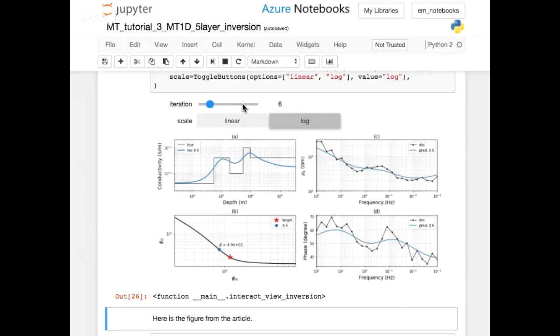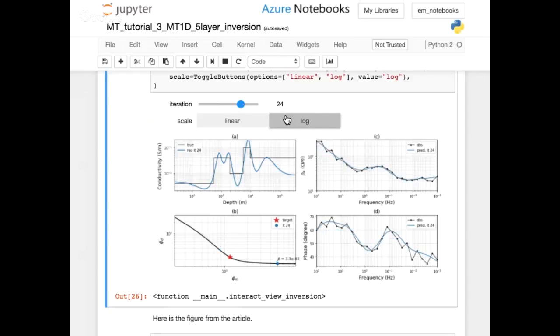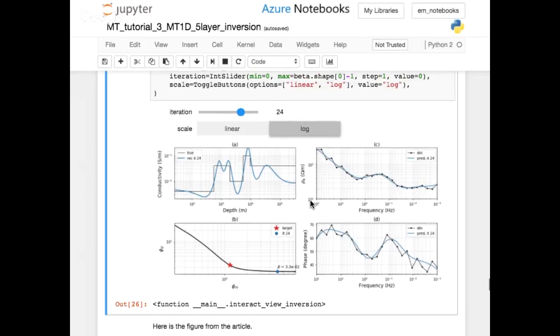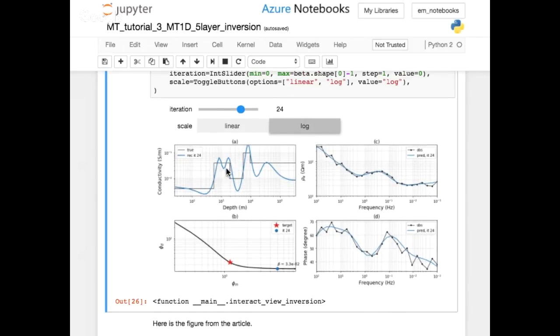If we go on the other side, what do you think the model will look like? So here, just like this. If we go too far, then we're actually trying to fit our data really, really well. And in order to do that, the inversion can just keep introducing structure. It'll keep doing that until we fit all of these little wiggles in our data. And that's no good because we've now introduced what looks like an extra layer in here. We're overshooting and undershooting our resistivities. And so that is the danger of overfitting.